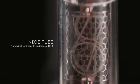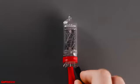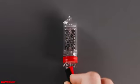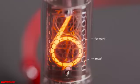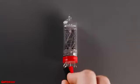We've got 10 digits, 0 through 9, all formed in wire like a filament kind of. But unlike a light bulb filament, it's not the filament itself that glows, but the neon gas right next to it due to some crazy science of the electrons flowing from the filament to this mesh. So to make these work, we just have to apply voltage from the mesh to one of the digit filaments.